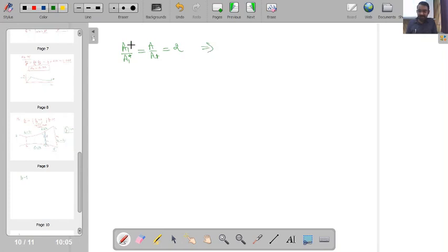Now what I can do, can I apply the area Mach number relation? Because I know A1 by A1 star. If I apply the area Mach number relation, then the Mach number at point 1 I can calculate from that relation, and I have to choose the supersonic one, because this relation gives us two solutions, one for supersonic, the other for subsonic. So here we must choose the supersonic one. Using that relation I will get the Mach number as 2.2. Please try the numerical calculations at your home, at your hostel. What I am doing is trying to give direct numbers; the formula also you have to apply over here. So M1 will be 2.2.